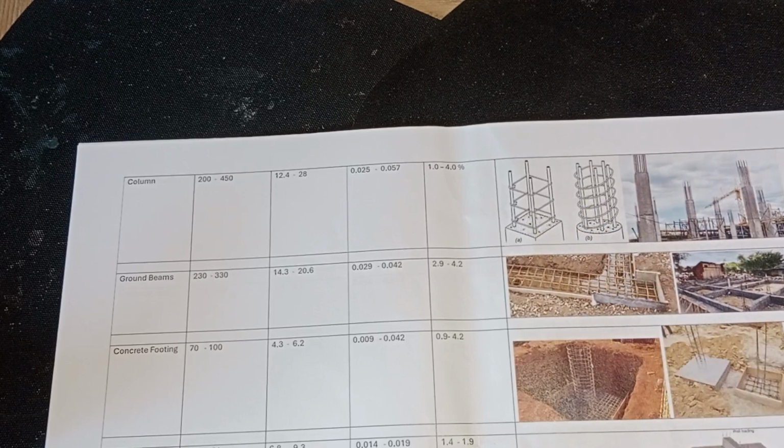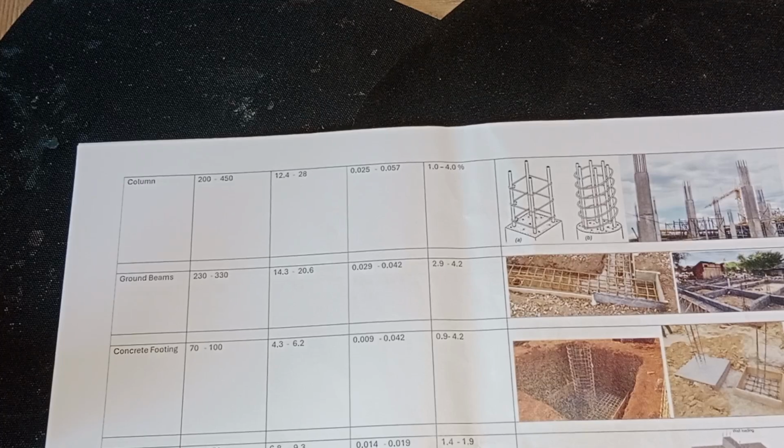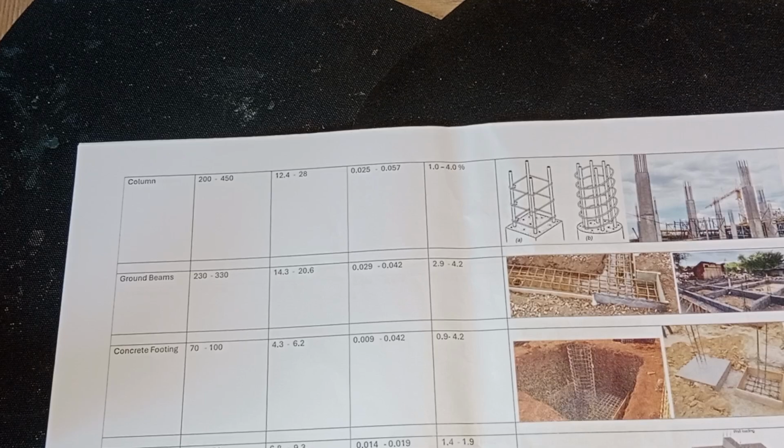Just one very common issue in column design, sometimes you're going above the range, even if you're going around 4%, even less than 4%, my suggestion is to try to increase the concrete capacity or concrete strength. Let's say if you're using 40 MPa, try to use 50, 65, or 80 MPa to have reinforcement ratio in the range of 1% or maximum 2%. It is much cheaper to use less reinforcement rather than using higher strength concrete.